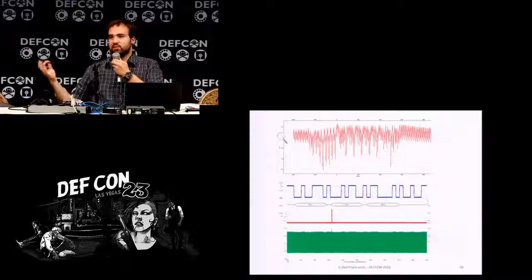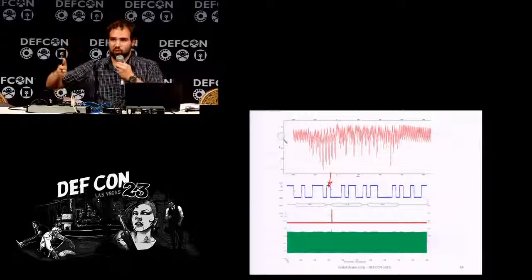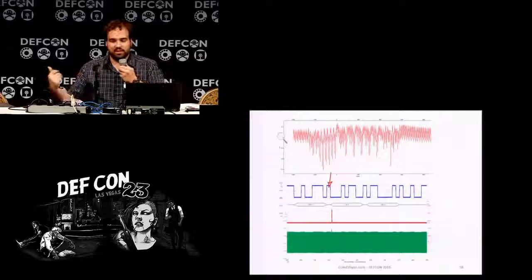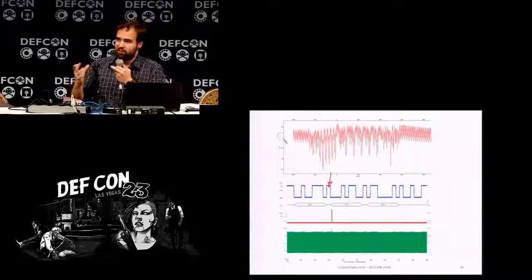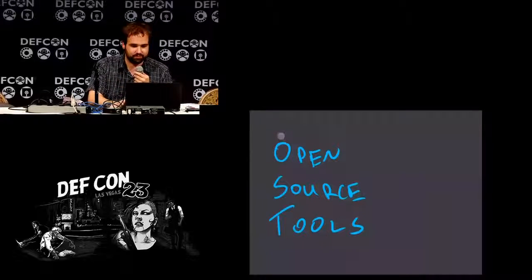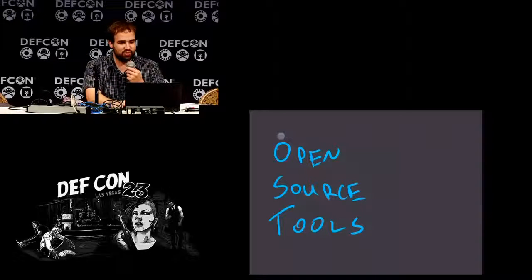The other thing you can easily do is triggering on the digital data. So when I send it data, I say, here's the request to encrypt, trigger when I send that request. For the side channel analysis, you can resynchronize afterwards. You don't have to have everything perfectly synchronized. We can do that as post-processing. It's not a big deal. All right, so that's a super quick run through of side channel analysis and glitching.